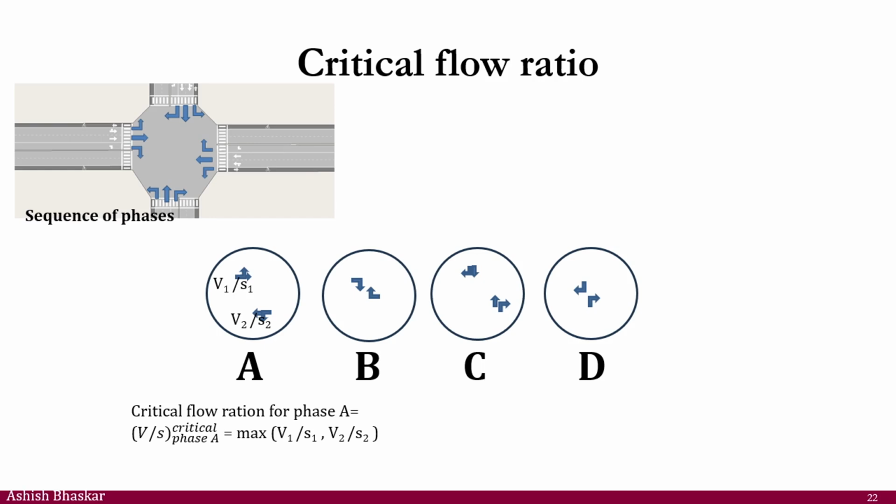You might have some kind of green time given to some approaches allocated with that one. Based on the width of the road and the speed at which the pedestrians are walking, you will have a minimum green time so that the pedestrians are served properly when you are giving the green to this approach. So that is also an additional constraint you're going to add.